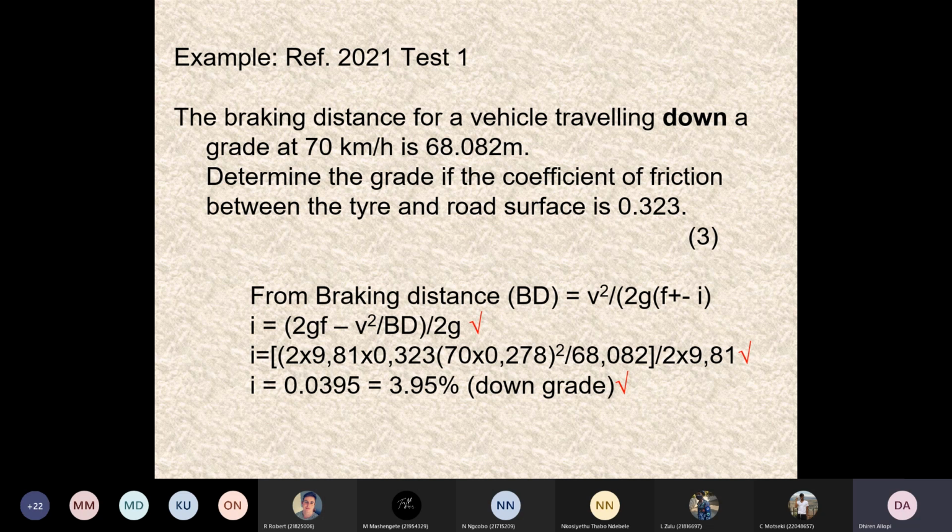Again, you could be given a table with the design speed and the corresponding brake force, or the brake force coefficient could be given to you. And the formula is different to the generic formula that we just looked at. I'm making this point clear because in the exam, I did ask for the safe stopping sight distance using the brake force coefficient, given the brake force coefficient, and many of the students used the generic formula and got it wrong. Although the final answers may be very close, you haven't answered the question. You should be using the brake force coefficient formula if the examiner specifies the brake force coefficient. So take note of that.